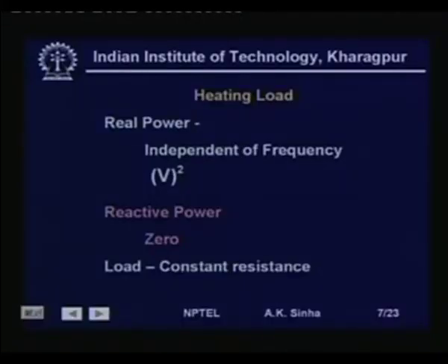Again, here the frequency has no part to play, because whether it is DC or AC at any frequency, except if we go to frequencies which are much higher, in terms of hundreds of hertz or kilohertz or megahertz, the skin effect does come into the picture, and the R value or the resistance does change, but at 50 hertz it does not affect it much.